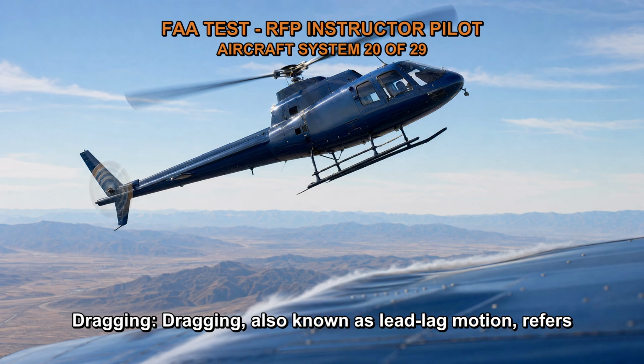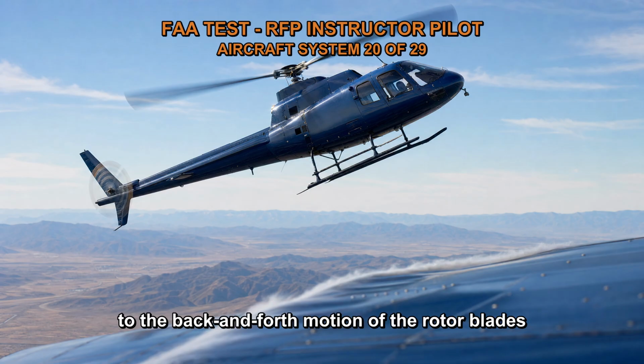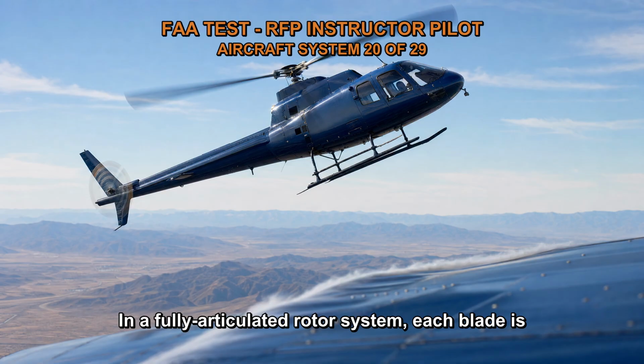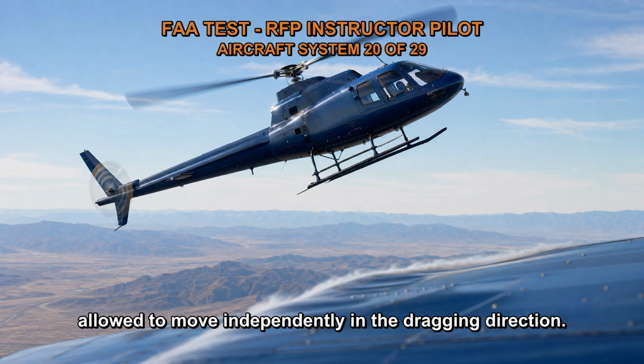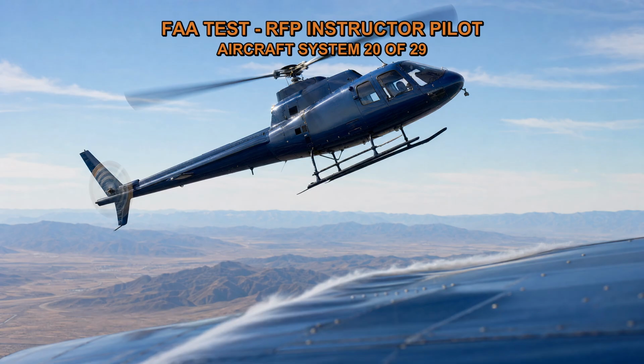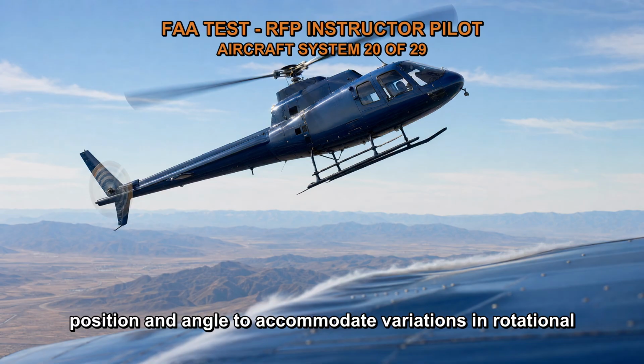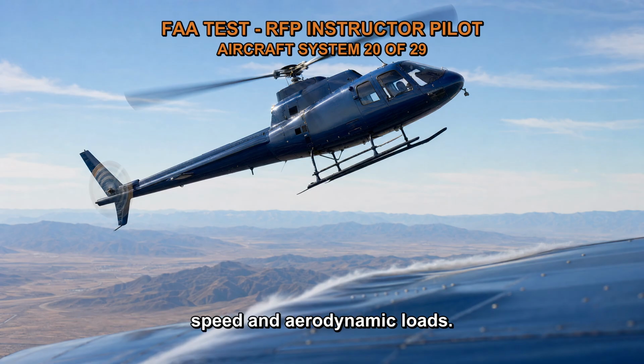Dragging, also known as lead-lag motion, refers to the back and forth motion of the rotor blades along their spanwise axis. In a fully articulated rotor system, each blade is allowed to move independently in the dragging direction. This flexibility allows the blades to adjust their position and angle to accommodate variations in rotational speed and aerodynamic loads.